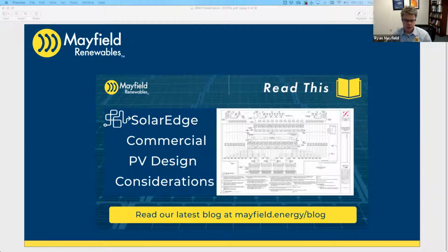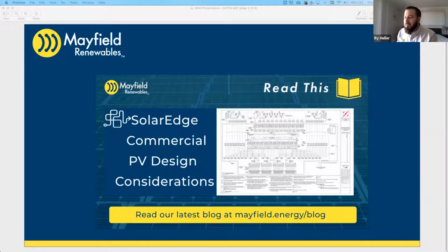Yeah. So there's the equipment requirements as well, right? Yeah, so you're talking about 230.79. Exactly. So in 230.79, it talks about what your minimum service rating size can be, and it's a little bit confusing. There are some different options in terminology about branch circuits versus service wires. But 230.79d basically says, for all other installations, the service disconnecting means cannot be less than 60 amps.